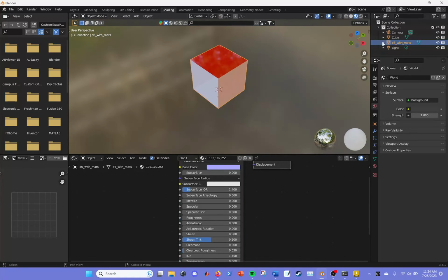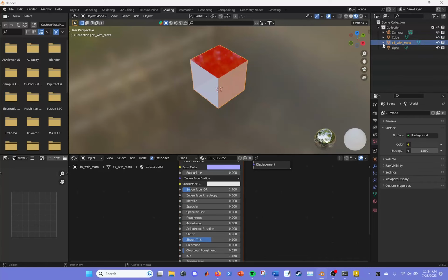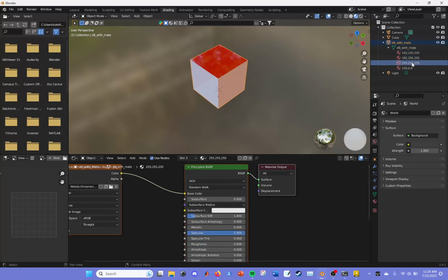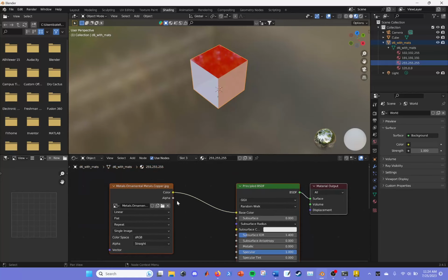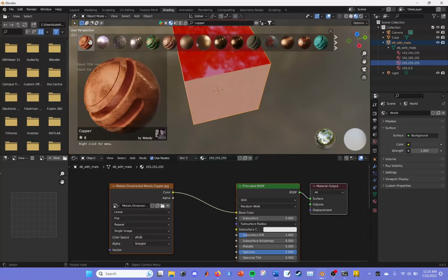But let's say that I think this copper doesn't really look how I expect it to. If I go into the scene collection and I find the name of my object, and then this little green icon triangle, and expand it, I can see the different material channels for the object. It doesn't carry over the names that Inventor had, which is a little bit frustrating, but you can rename them by double-clicking on the name at the top of the Node's Editor panel. Luckily, the Inventor name is based on the original RGB values for each material. Sometimes, if a material doesn't load in altogether, you can use those RGB values to closely approximate it in your Blender file. But let's say that I mess around with the settings and I still don't like it.